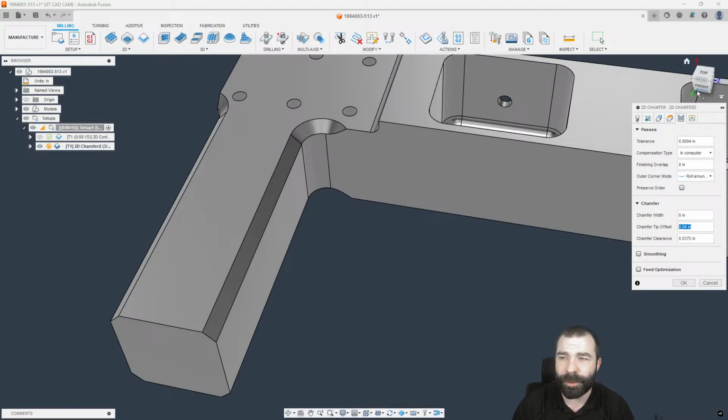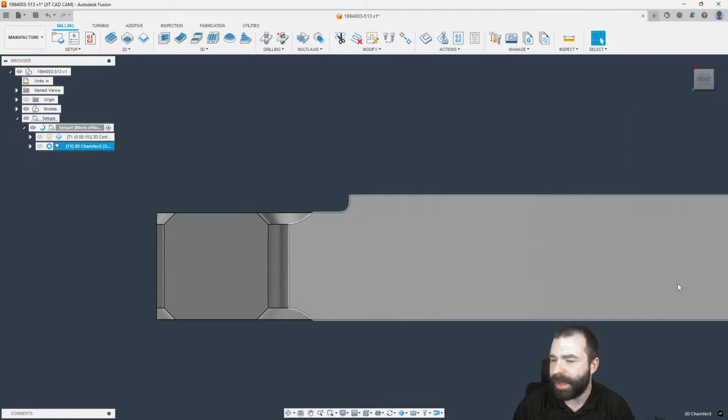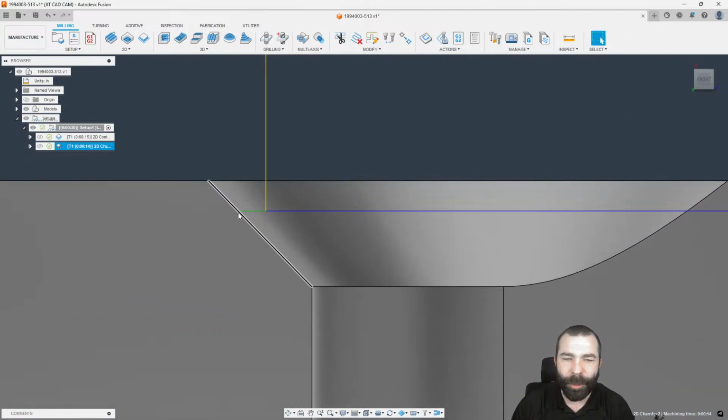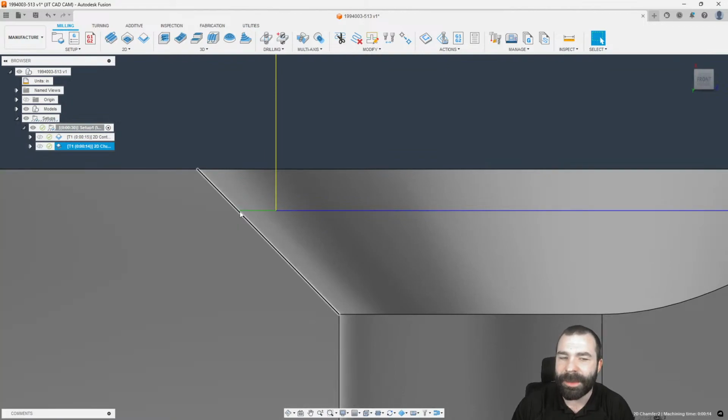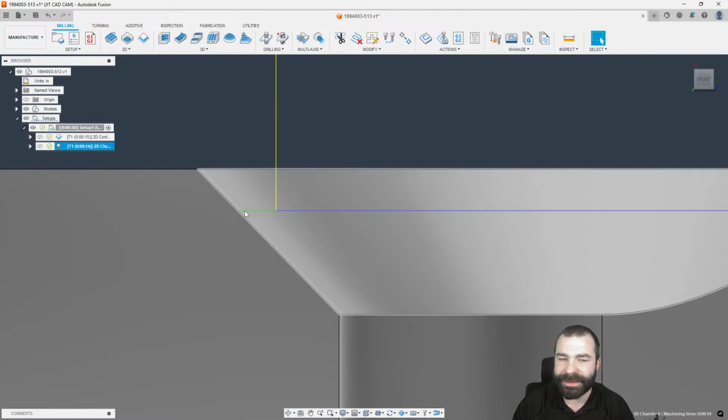from that contour, right? So knowing this contour is up here at the top, I'm going to go ahead and hit OK. And what you're going to see is, of course, we're offset 40 down. But what you're seeing is based on the center line of my tool. This tool doesn't have a flat. It is following that chamfer exactly as needed.